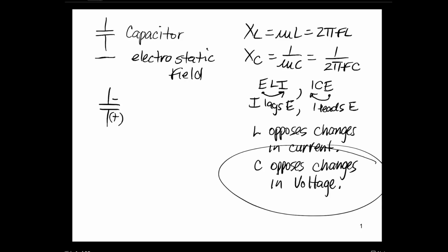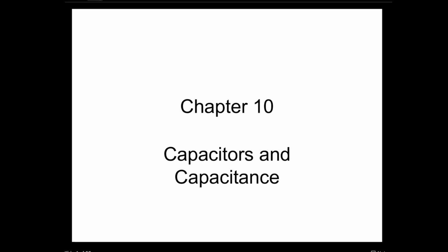And that would be a capacitor. That's how come you have capacitive filtering in power supplies. If you were to open up some power supplies in the lab and look under the hood, so to speak, you would find capacitors of varying sizes in there that are used to filter the output from the rectifier in that power supply. So that's what we're talking about today, capacitors. This is chapter 10 of your Robinson Miller book.